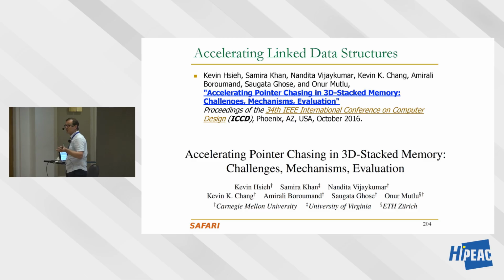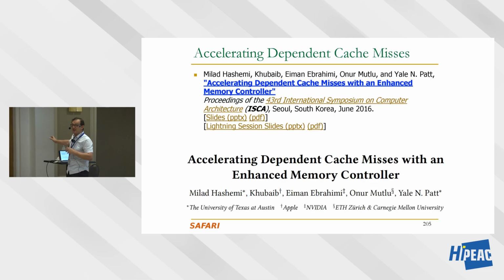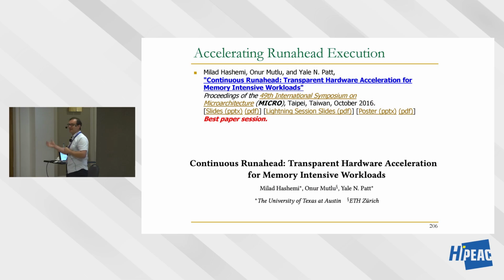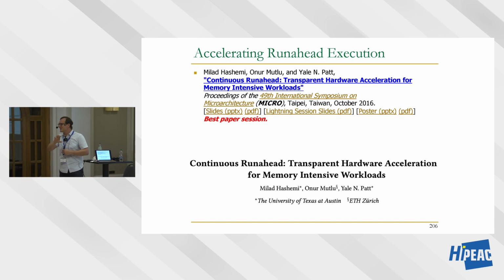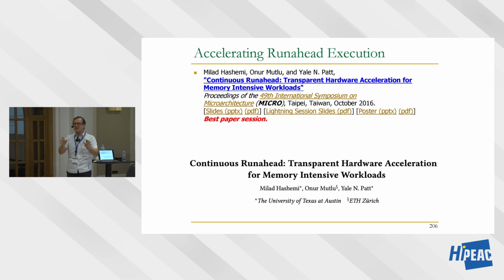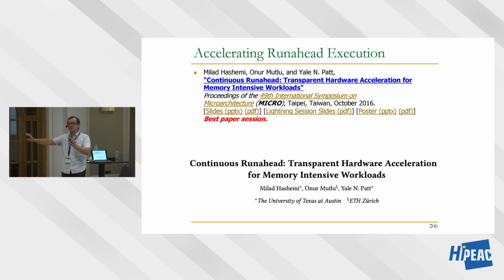So we've accelerated pointer chasing in 3D stacked memory. We've accelerated actually transparently cache miss processing, if you will. It's more than that, but you can look at it. We've accelerated my PhD thesis. In the memory controller, you can actually do prefetching, like using run-ahead execution. This is a much better way of doing my PhD thesis, in my opinion. In my PhD thesis, we basically speculated in the processor to execute instructions when you stalled otherwise.